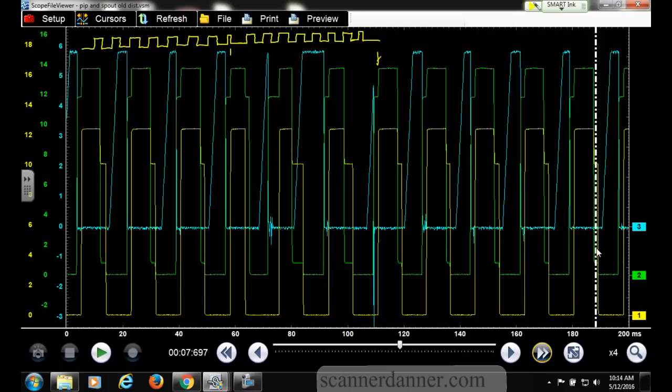Does that make sense what I'm talking about with this guy here and this guy here? Every distributor rotation we have this smaller notch, physically a smaller window that identifies number 1 cylinder. So our firing order then, if this is the case, it should be this one. This is number 1. Okay? Let's see if we did this right. Yeah. This is number 5. 4. This is number 4. 2. And this is number 2.